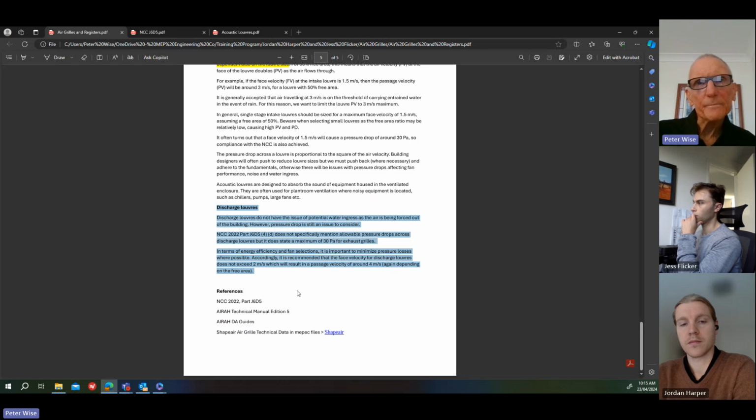The static head on a pump is, if you've got a pump down the bottom of a building and you've got water pipework that goes all the way up the building, the static head is the head of that water above the pump. But when the pump is turned on and it's pushing water through a system, it's a dynamic pressure. So that's what we're going to be calculating. And that'll be the basis for pump selections, which we'll go on to after that.